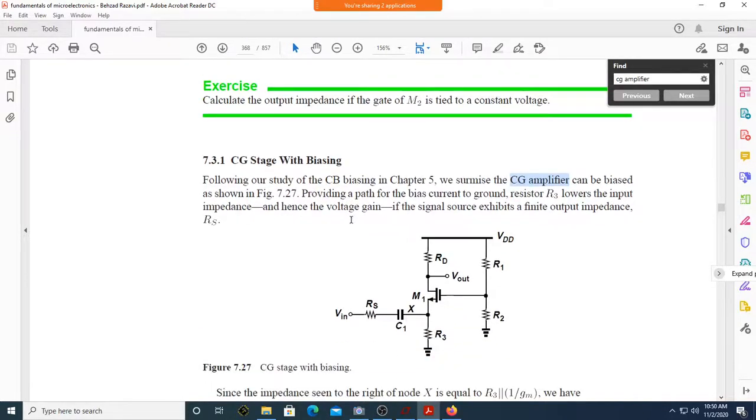See this now. This is the actual circuit how it looks. Usually you are going to have a coupling capacitor to ensure blockage of DC, correct? And you will have a resistor R3, because whenever I put a capacitor here, if there is a DC drain current flowing here, then DC current is not at all allowed to flow if there is no R3.